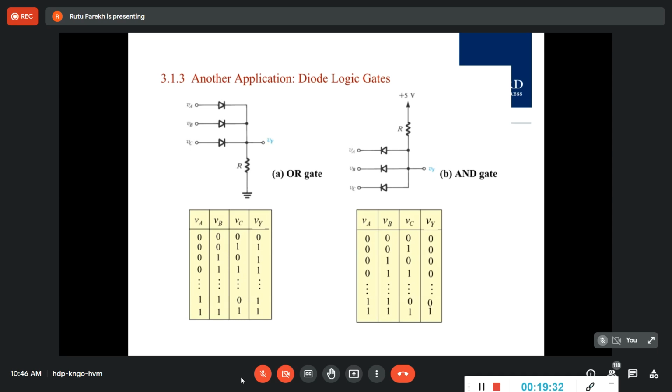And the rectifier, all these things we studied, was a power unit, which are analog circuits. Digital is 0 and 1. Since a diode is a two-terminal device, it is a switch, on and off. You cannot make an amplifier using the diode, remember. It's not a transistor. It's a diode, meaning two electrodes, and on and off. So using this diode as a switch, you can make logical circuits, digital circuits.